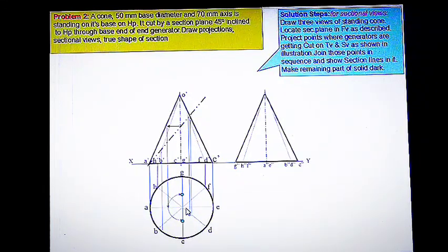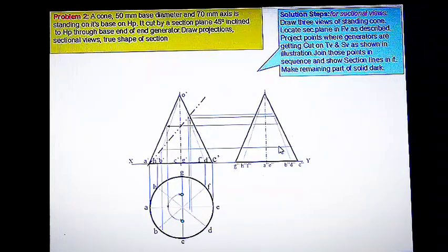Okay, now we can get these 2 points on up and down of this horizontal line. Now we have to project these points, these intersecting points, to the side view by drawing horizontal lines like this and get this corresponding intersecting points one by one.